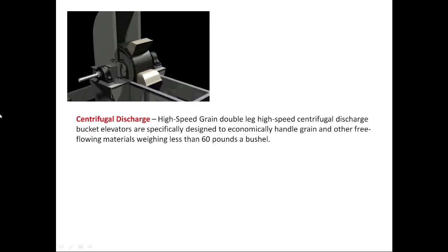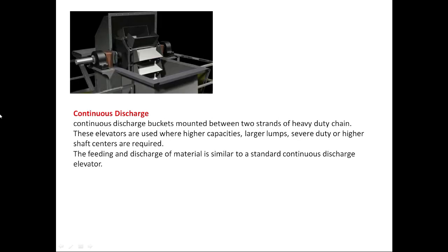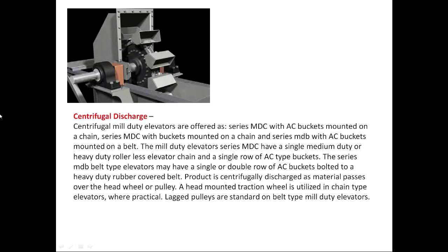Centrifugal discharge bucket elevators are specially designed to economically handle grain and other free-flowing materials weighing less than 60 pounds. Continuous discharge buckets are mounted between two strands of heavy-duty chain. These elevators are usually used where higher capacities, larger lumps, severe duty or higher shaft centers are required. The feeding and discharge of material is similar to a standard continuous discharge elevator. Centrifugal discharge.